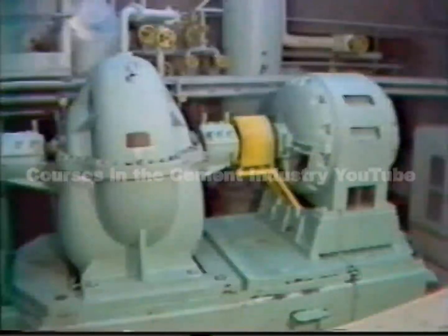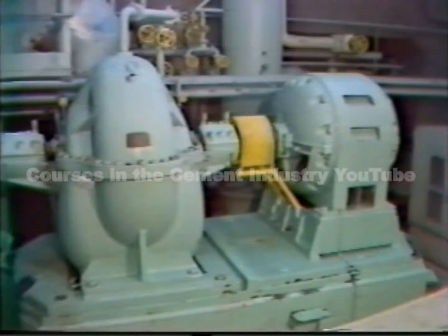So when viewing machinery from the side, you can detect misalignment in the vertical plane. It could be angular or parallel. In a lot of cases, you'll find a combination of both. In other words, the shafts will be at an angle to one another and offset.